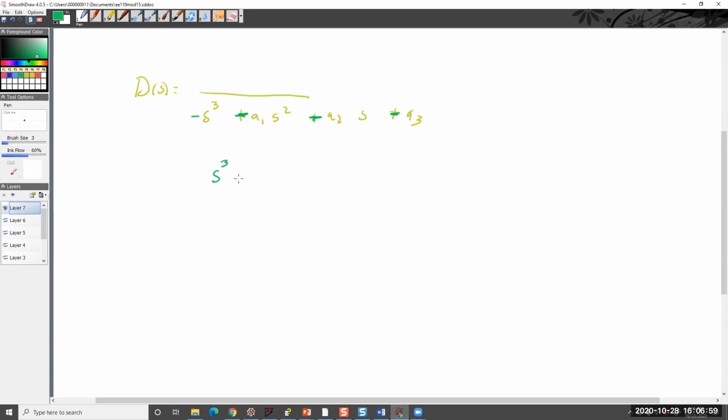Now, what wouldn't be in control is something like this, where I have a sign, or something like this. They all have to be here. Anything missing, and you're going to get at least one pole on the right-hand side, equal to or greater than the right-hand side. And if you have one change of sign, because we're not concerned with the exact number of poles and where they are, because to actually go through it is quite involved, and sometimes it's very hard to determine, you know you've got at least one pole in the wrong place.